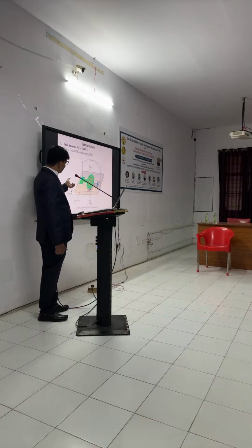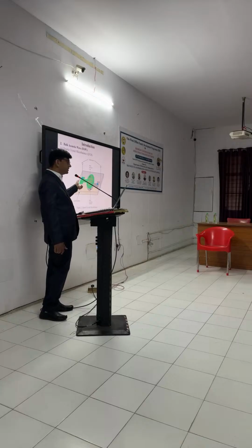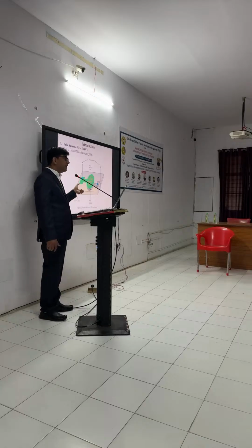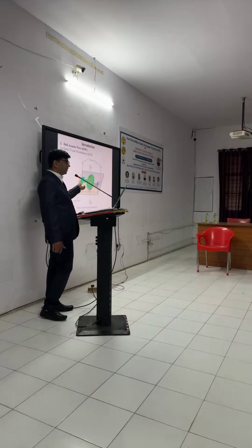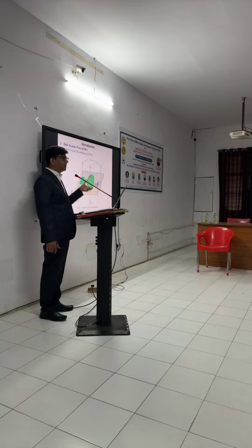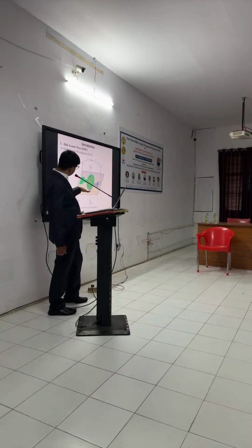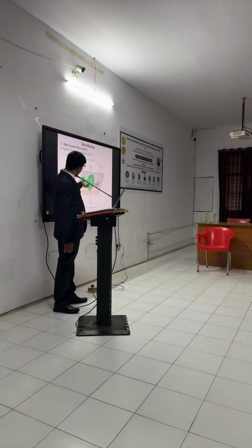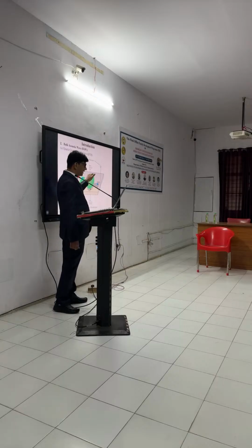So why is this resonant mode generated? Basically we have a perfect confinement of the acoustic signal within this piezoelectric layer. What do you mean by this confinement of the acoustic signal? Once we have an excitation by an electrical signal through the top and bottom electrode, an acoustic wave is generated, and it travels between the top electrode and bottom electrode. If that is not done, what will happen? Our resonant mode will disappear.